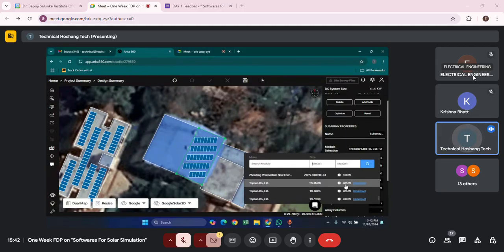This depends on the actual available space, whatever watt panels you need to utilize, and also on the inverter which you are using. Some inverters are specifically designed for higher utilization of current, with a maximum input voltage of 110 volts, and maximum current of almost 45 to 65 amps.